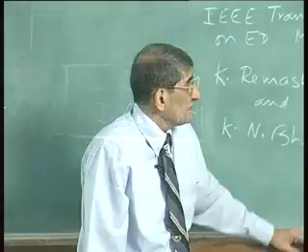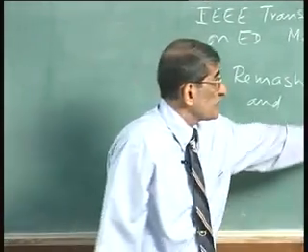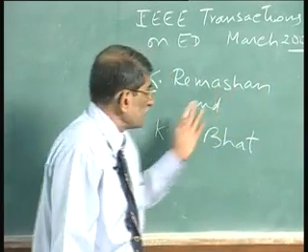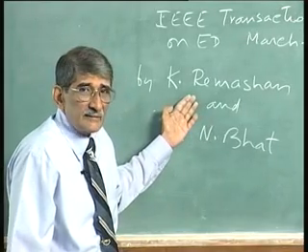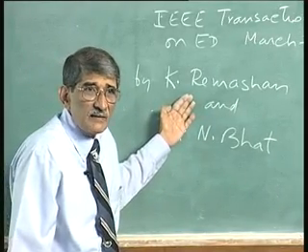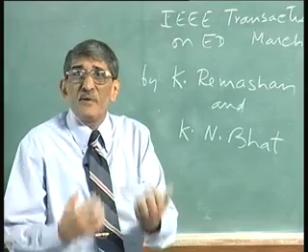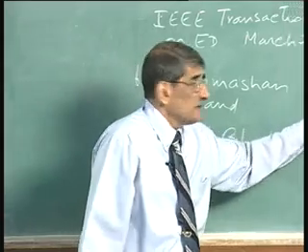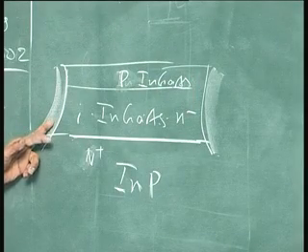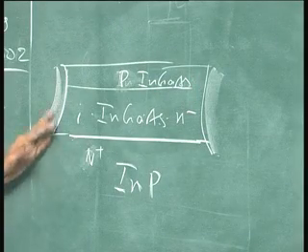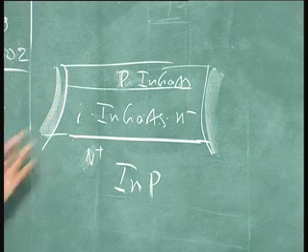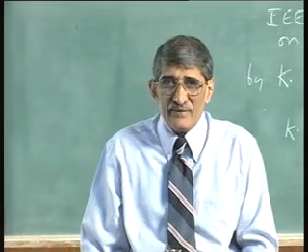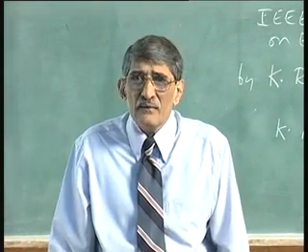So, when you use ammonium sulphide, it is not sufficient, you put a coating of another dielectric material. One of the things that is done is PECVD nitride, which worked out very well with annealing etc., because when you deposit PECVD, there are some damages which come up because of the RF. But here, what we have tried out, in fact, as part of some MS degree program, passivate with ammonium sulphide and then deposit polyimide. Okay, just spin polyimide. Very easily you can put a coating of that. That gives excellent leakage current.